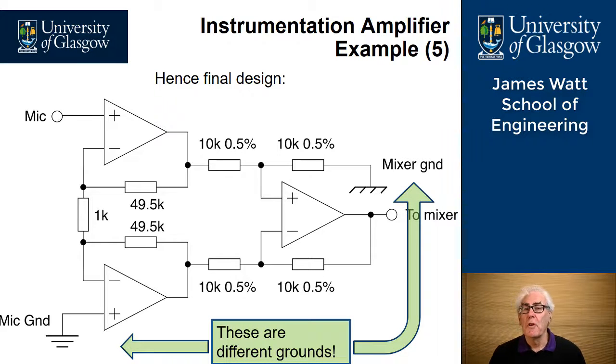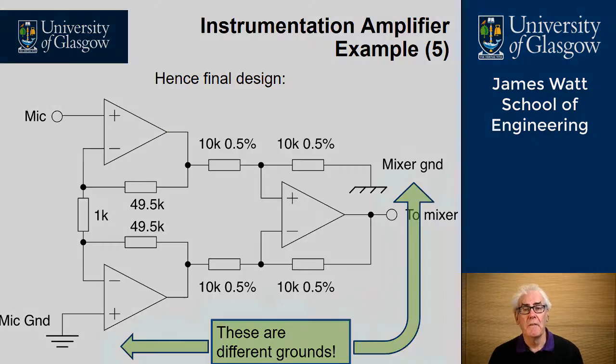The key thing to note in this example is the microphone ground is not the same as the mixer ground. They are two different sources of signal, and in the example we've given, there was a 1 volt signal across those two grounds. But using this approach, we would end up with a high quality audio output to the mixer, in the presence of a relatively large common mode signal of 1 volt RMS at 50 Hz.